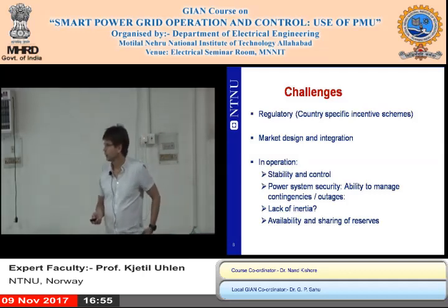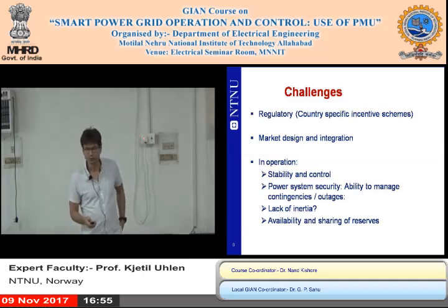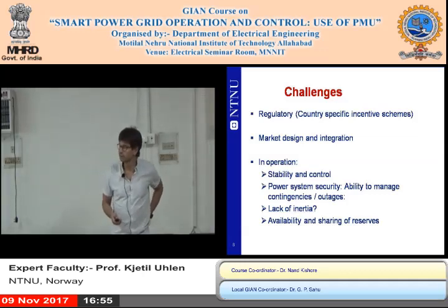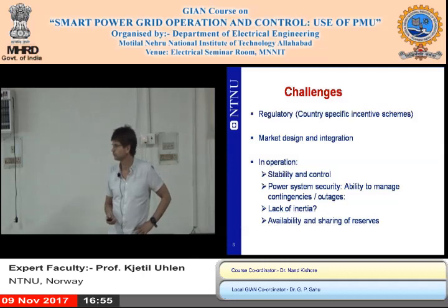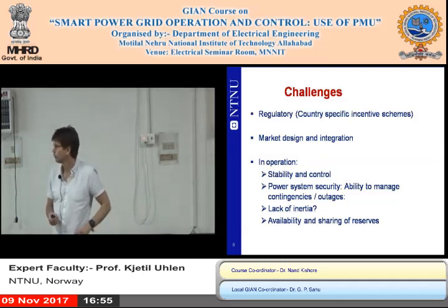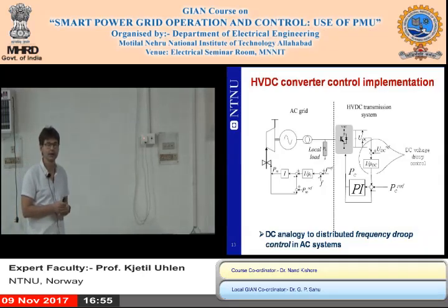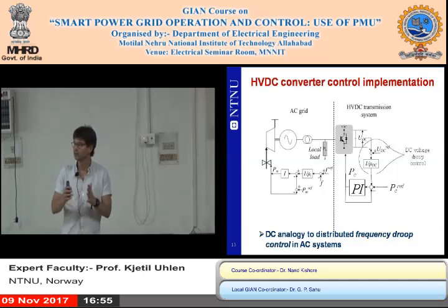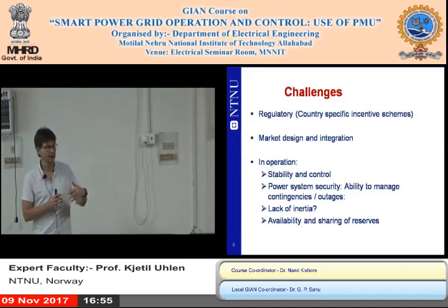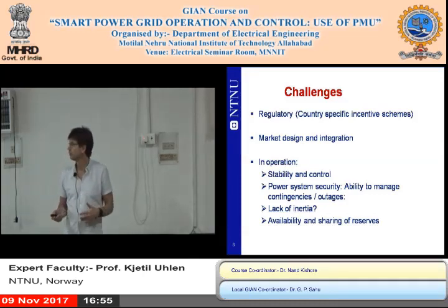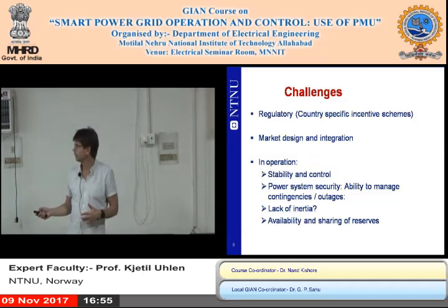And then we start looking at the basics with respect to control of a multi-terminal HVDC grid. You know that when you deal with the power balance in an AC grid, that is very much about adjusting the speed droop of the turbine governors to provide a balance.